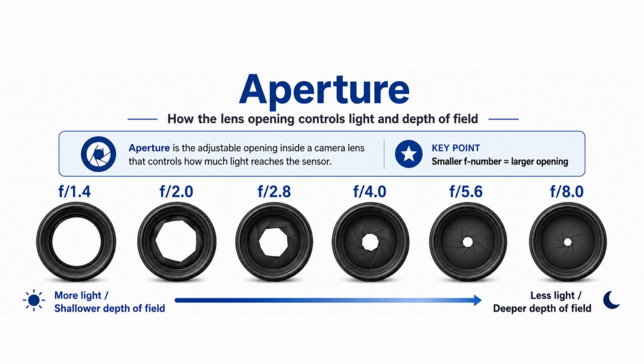A wider aperture produces a brighter image and helps in low light conditions, but reduces the depth of field. A smaller aperture allows less light, but keeps more of the scene in focus. For vehicle navigation cameras, aperture must balance brightness, low light performance, and terrain sharpness.